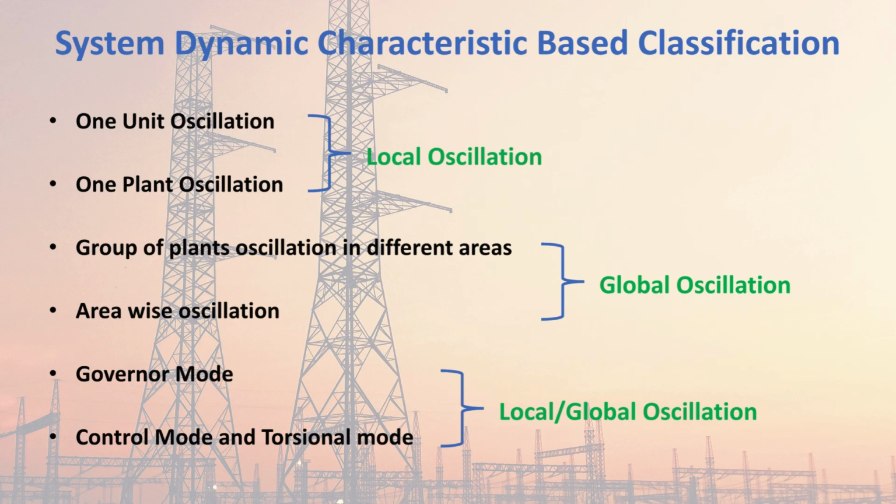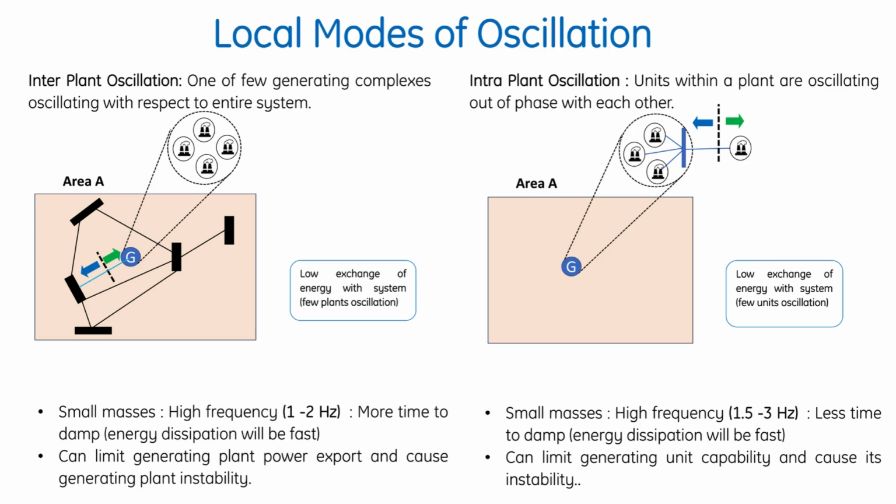The sources generally identify 3 major types of these characteristic modes. Okay, let's start with the faster, more localized ones. Those would be the local modes. As the name suggests, these typically involve just a single generating unit or maybe a small group of generators at the same plant swinging against the rest of the power system. Okay, like one machine oscillating relative to its neighbors. Pretty much. You can often visualize it as swinging against the local substation or the immediate connection point, the bus bar. They tend to be faster, maybe in the 1 to 2 hertz range.